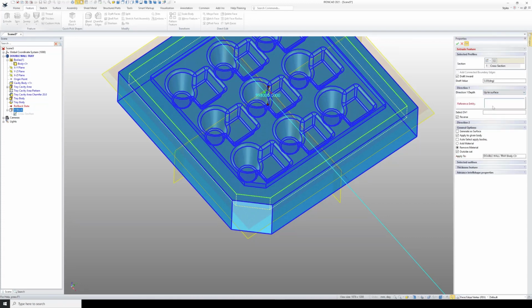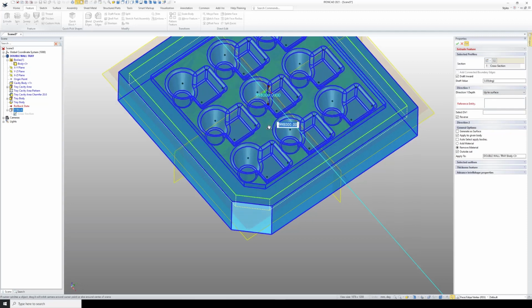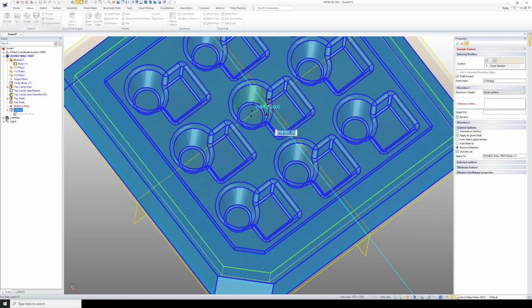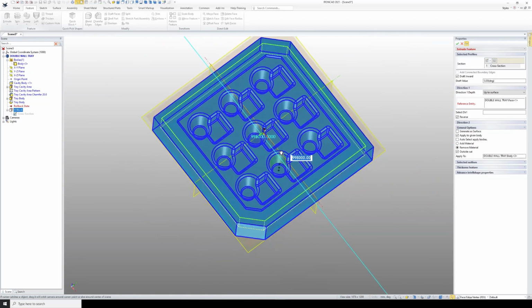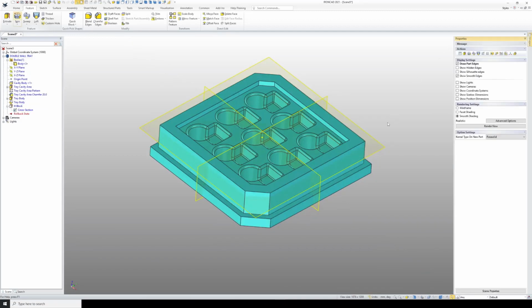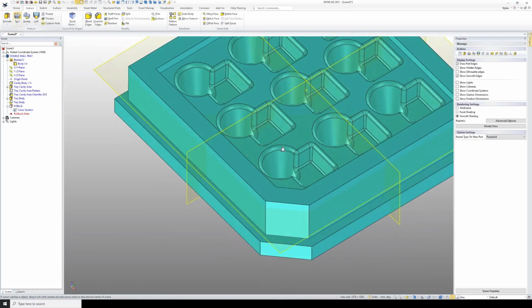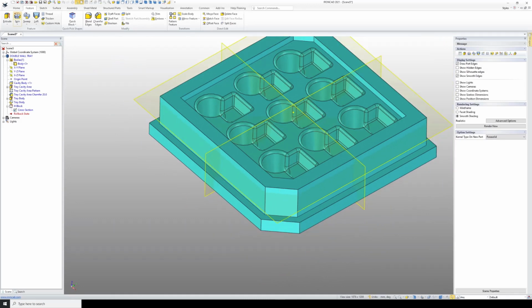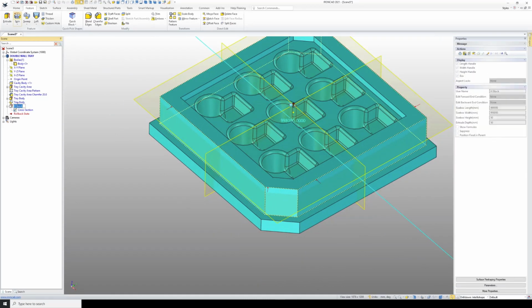So there's a particular surface that I want, and I'm going to choose the original cavity here and that bottom face of the cavity. So what I'm saying is that I want that outside cut to match that bottom face, and we'll go OK. Good, I'm happy with that, and so we'll give it a name. So again, tray body, just to help keep track of it,